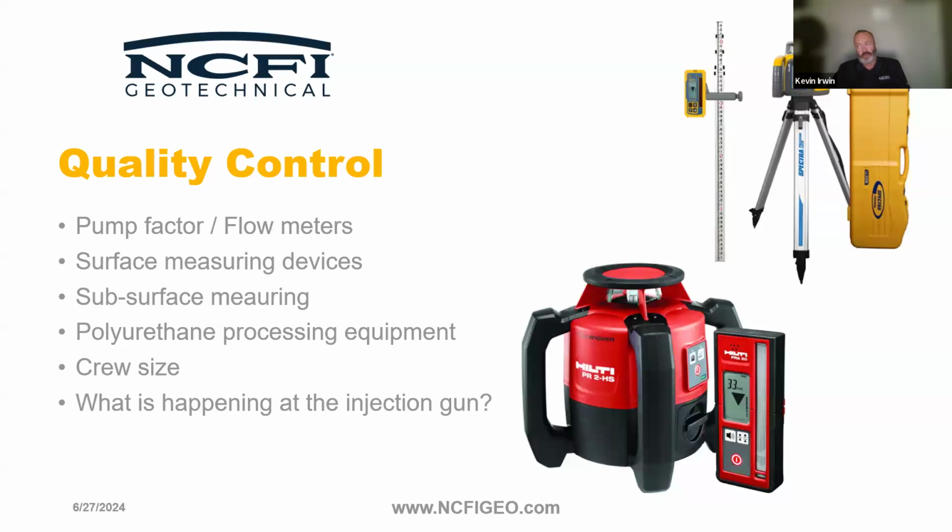Crew size is going to be a big factor in quality control as well. Two people minimum, but I always preferred three to four on a deep injection project that's going to be more than just a few injections. We need people that are going to be monitoring back at the rig. Need people that are monitoring lift around the area being injected, so don't try and do it with too few people on a crew.